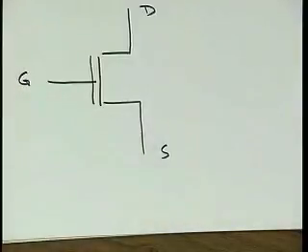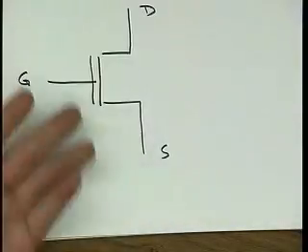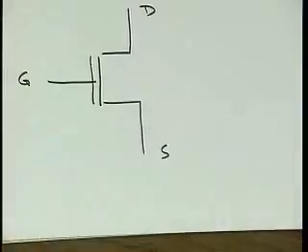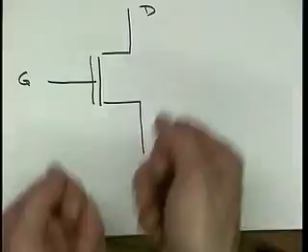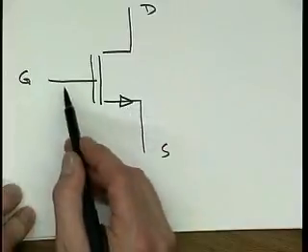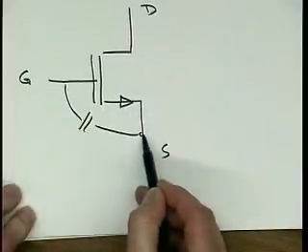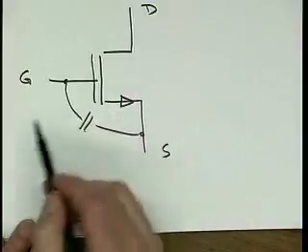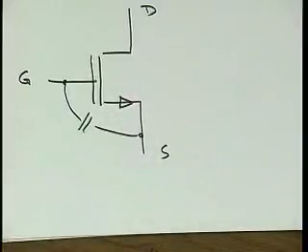this is sort of our thinking of the device, right? We have really 3 terminals that we care about, and we know the voltage on these terminals, or we could measure them with a voltmeter. So we really know about these terminals. So it's only natural that we say, heck, we want to model these devices by capacitors that are between these nodes. Well, that unfortunately just doesn't work.